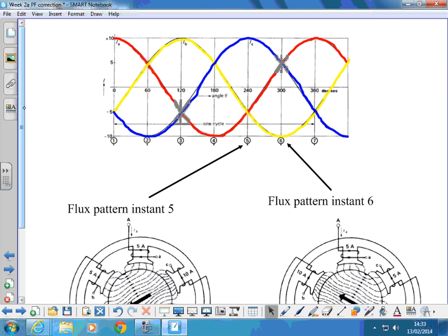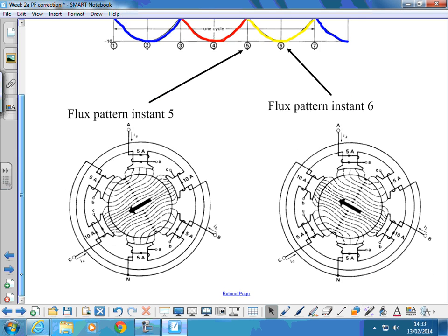So in one cycle of the 50 Hertz mains, this rotor would rotate once. Okay, that would be termed a 2-pole motor. Each phase has got 2 poles associated with it. More importantly, you'd call that 1-pole pair. And again, we'll come back to that in a little while. But that would be called a 2-pole motor because there's only 2 poles per phase.